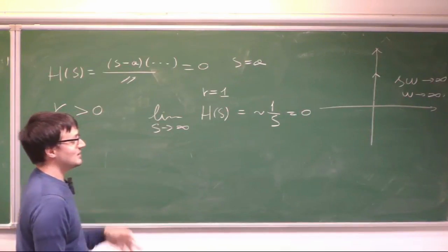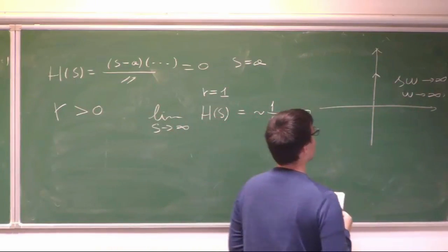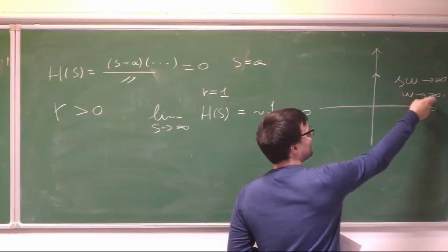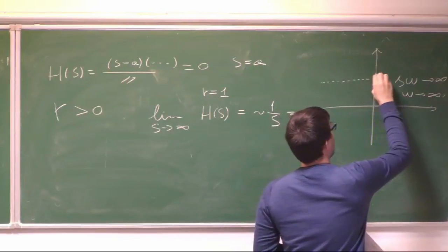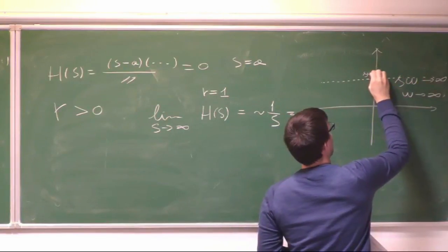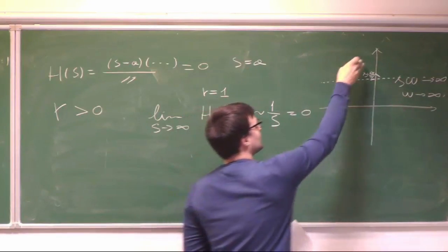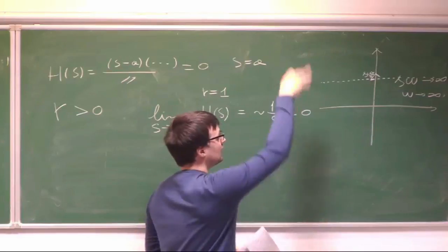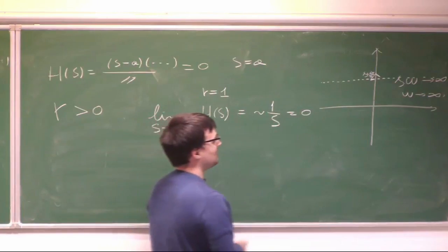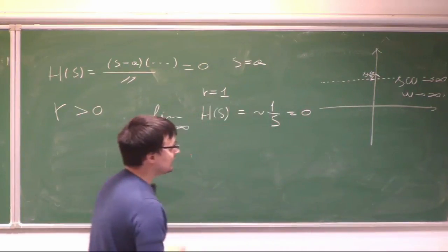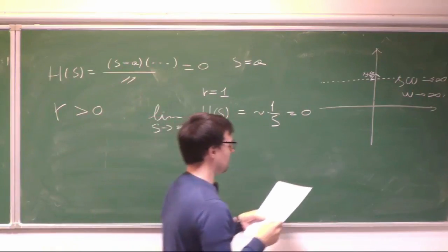But what is the maximum frequency in discrete time? In continuous time, omega is going to infinity, but we know that this frequency is not reachable in discrete time, because if we go over j omega s divided by 2, we end up in the secondary strip. The secondary strip is mapped in the primary strip, and so are all the other strips. So everything that happens after j omega s divided by 2 is actually mapped inside the primary strip. In discrete time, the maximum possible frequency is the frequency j omega s divided by 2.